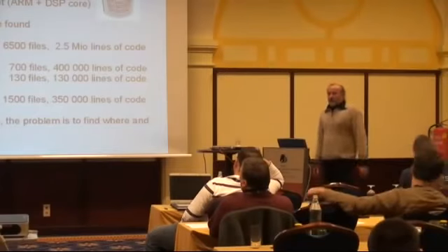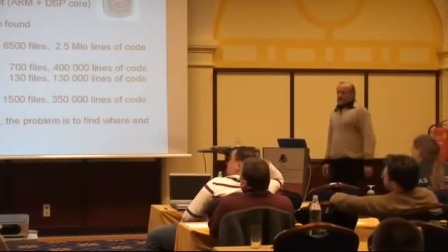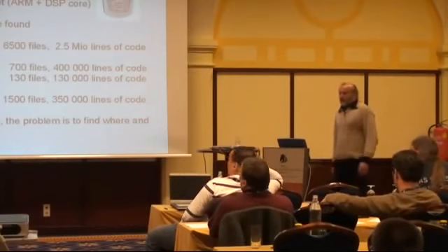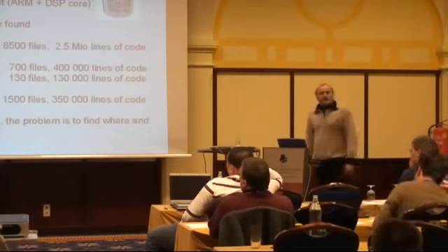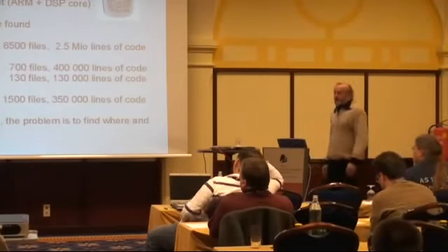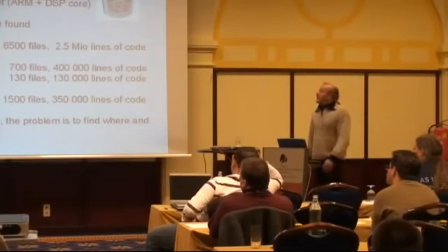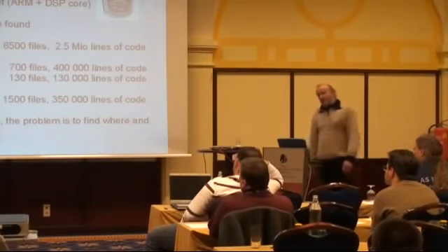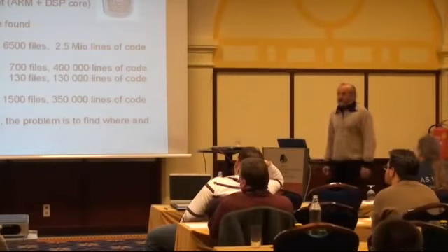The chipset is called Calypso. It consists of 3 chips. One is the main processing core, which contains an ARM and a DSP processor. And then there are 2 supporting chips. One is for the digital baseband, the other is basically the RF transceiver.